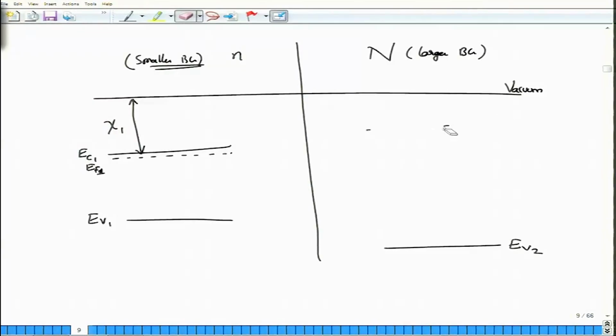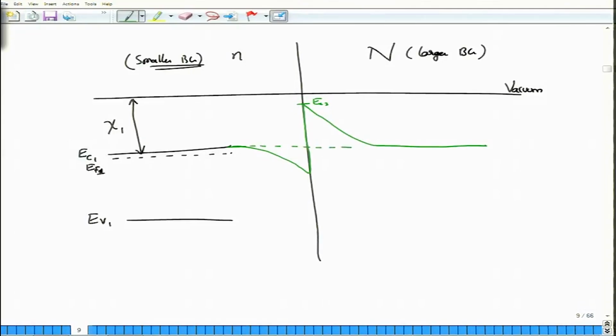So, I am going to write down the band diagram. Do not worry if you do not really understand how these band diagrams are made, because there is a complicated theory behind it, but the basic idea is this: EC1, as you gradually go towards the junction, would fall somewhat, creating a well here in the middle, and then there is a spike right away. And what does the spike do? At the spike, it will actually reach EC2, where the previous EC2 was, and then gradually drops off, eventually being almost equal to EC1 far away from the junction. So, this is the change that has actually happened.